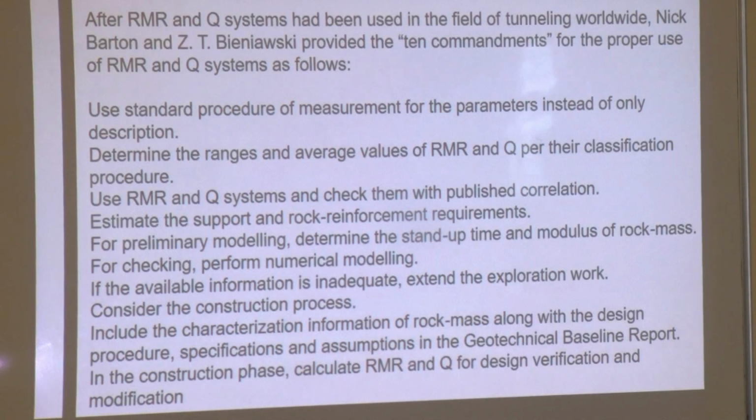These are the 10 comments put together by Bieniawski and Barton. These are the two big men who proposed rock classification systems, and they have told us, the practicing engineers, that you need to take care of these 10 parameters. So when you use our RMR and Q system, this is very, very important.